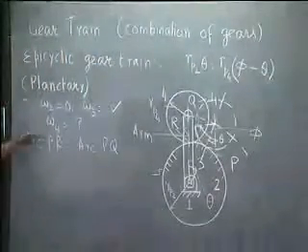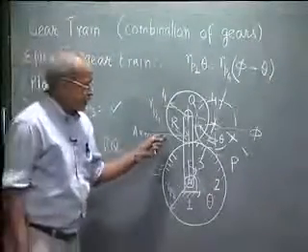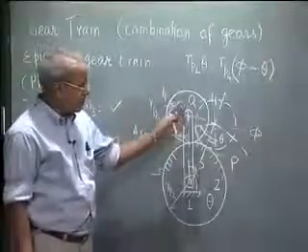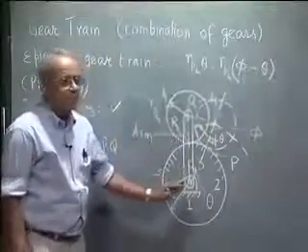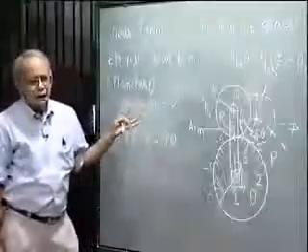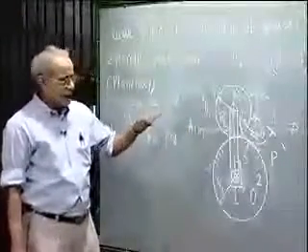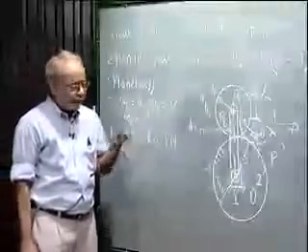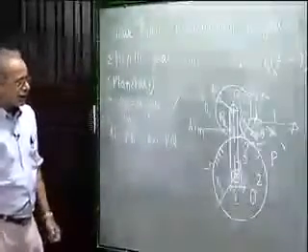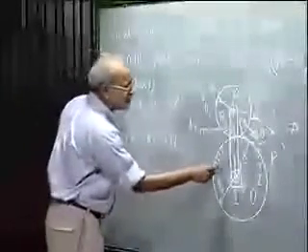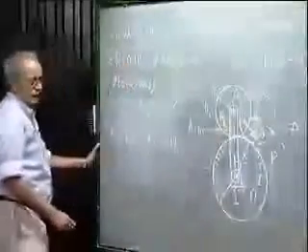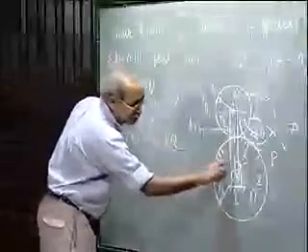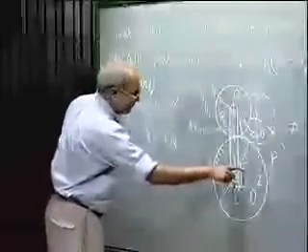Now what we shall see is that the relative rotation of the gears with respect to the arm still follows the teeth law, that is, inversely proportional to the number of teeth, with appropriate sign. Let me see what the rotation of the sun gear with respect to the arm is. Sun gear was fixed, the arm rotated theta in the clockwise direction.